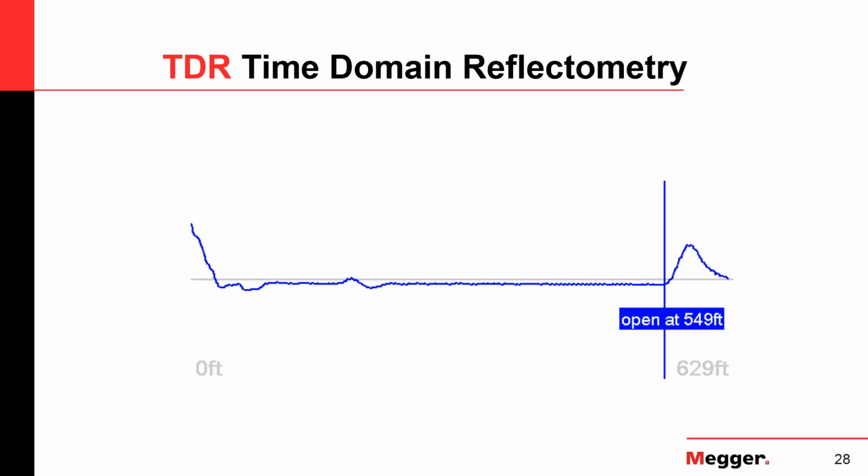It is important that you have an expectation when you go out there. If you know the cable is 1,000 feet long and the TDR tells you 980, does this meet your expectation? Or does it not? Is it close to the 1,000 feet, or do you have a very exotic fault that is right there at 980? There's an open conductor or something like that, and you don't actually see the physical end of the cable. But 980, 990 out of 1,000, that sounds pretty good as a first approximation. So you have to have an expectation.